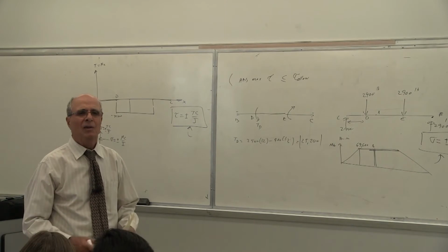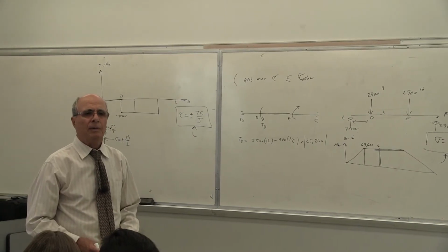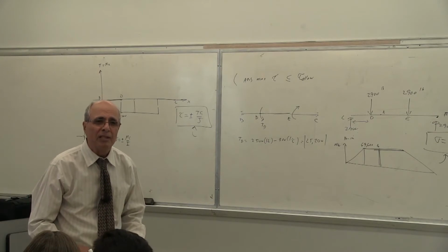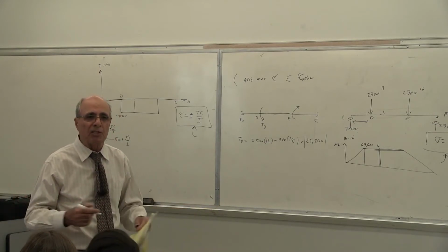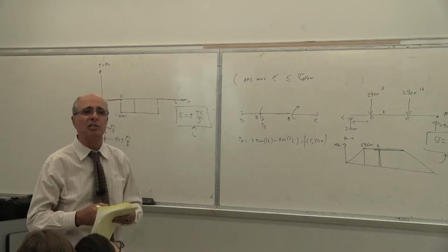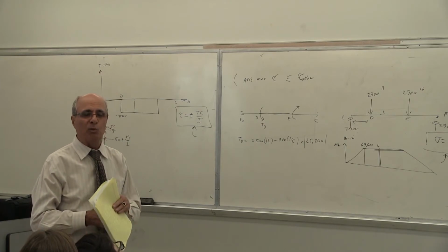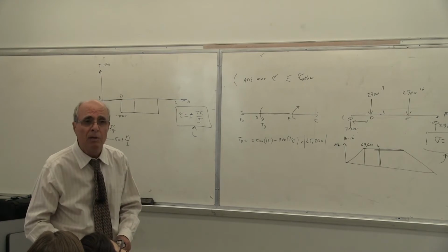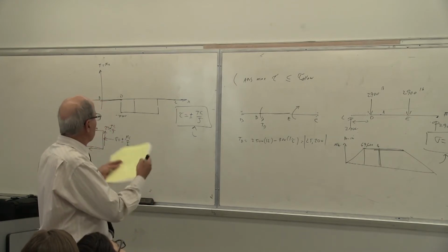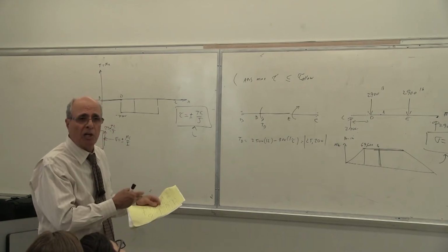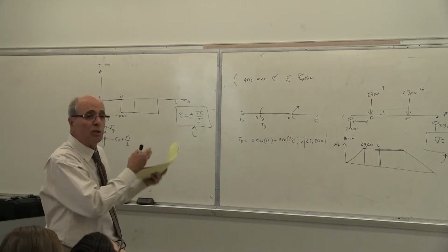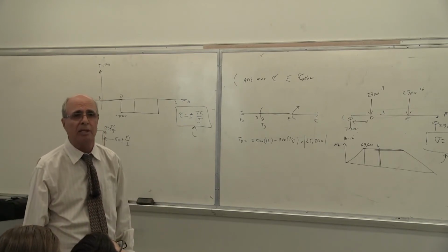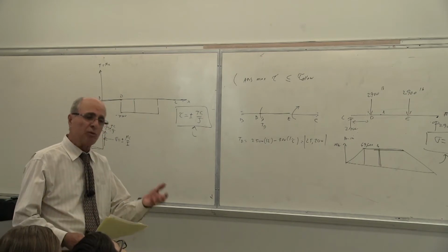Yes? I'm not sure why you made a negative on the torque diagram. I said it doesn't make any difference. Either it's going to be up or it's going to be down. This is for discussion purposes. I did not say for this particular problem whether it is up or down, and you will see in a minute why. I'm saying it could go plus or could go minus. The other one, I can draw either way. I said normal stress on the top is compression. If I change the direction of the moment, it's going to change. Is that correct or not? So yes, you are right.